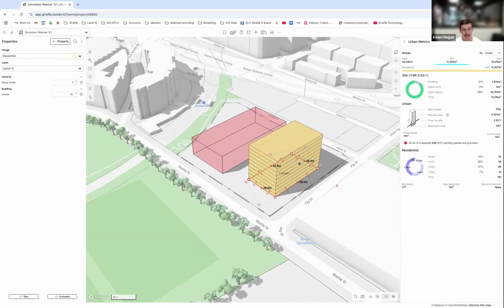And so just returning back to my earlier comment and rounding that out, this residential usage is like a starting point. So we supply you with this. We've made some assumptions, and within your workflow or your company, it's up to you to configure this and change it to suit your particular workflow. So maybe your residential buildings don't have a floor to floor of, say, 3.6 or something like that, and that's your standard. And what we can do is configure these settings.